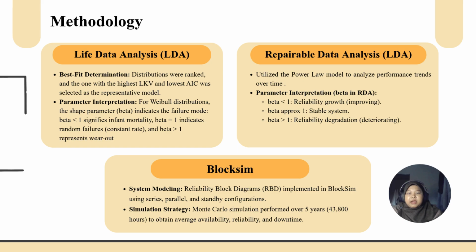Finally, these failure and repair distributions were integrated into BlockSim. We constructed a reliability block diagram, which is RBD, using series and parallel configurations to simulate 5 years of plant operation through Monte Carlo simulation. This gave us our final averages for availability and downtime.